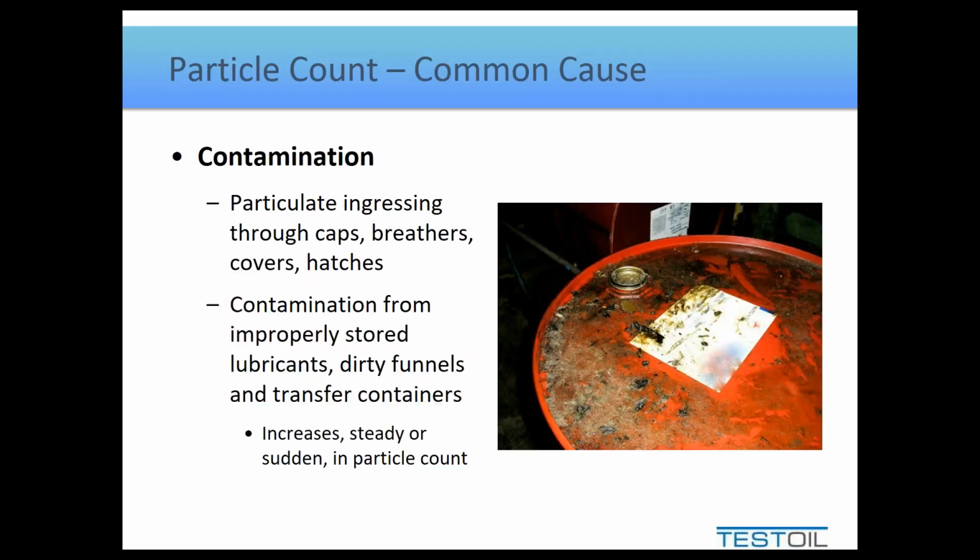They will find their way through every opening, whether it's a dipstick, a hatch, a cover, a fill cap, breathers, you name it. They will also enter the oil through the use of any contaminated handling mechanisms. So whether it's a dirty funnel, pail, fill jug, anything like that will always lead to an increase in particle count. But one of the things I do like to stress is, as I mentioned, new oil tends to be at least about 8 times dirtier than is commonly required as an upper limit in most operating systems. So the mere fact you add new oil can increase the particle count, even if you're doing everything properly, so long as you've not pre-filtered the oil.